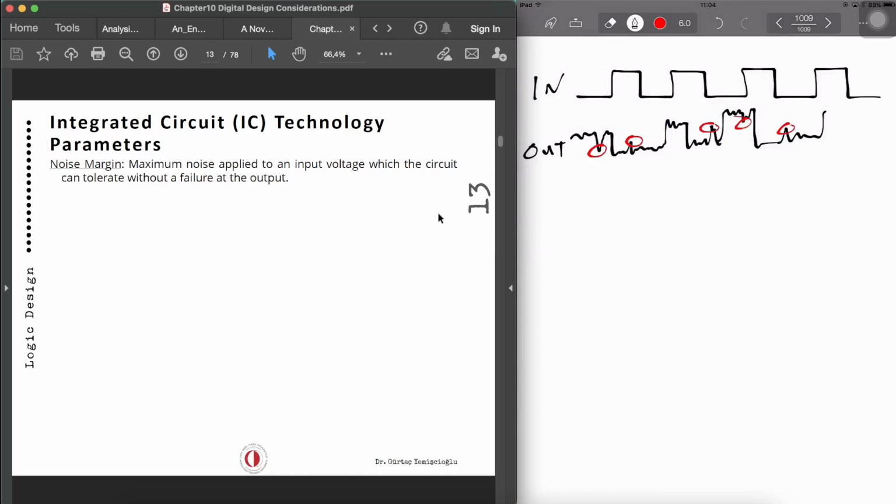Now, if you do remember in chapter 1, we mentioned the threshold voltage of a transistor. So when it reaches certain points like 0.7 volts, your transistor is going to be on or maybe off. Now, as you're expecting a 1 over here, and because of the noise it's degraded to somewhere here, that might turn off the transistor.